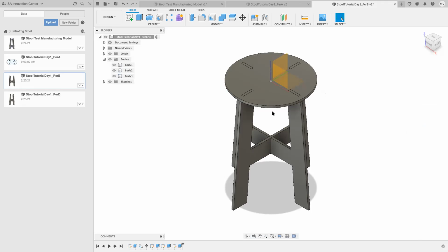All right, so the next thing I want to talk to you guys about is dog boning. The truth is that these things won't be able to perfectly lock together because of how we're manufacturing this. We're using a CNC machine, right? A CNC machine cuts with a round bit, okay? Think of a drill bit. I have one here, I'll show you guys.